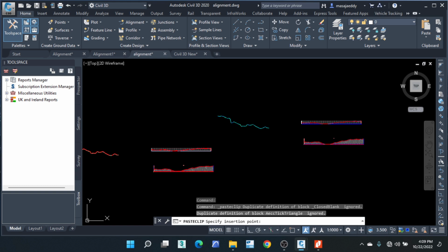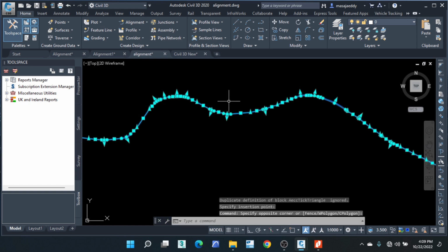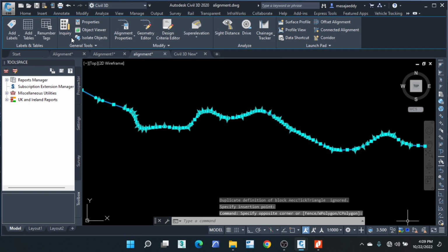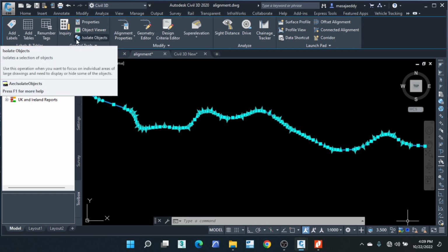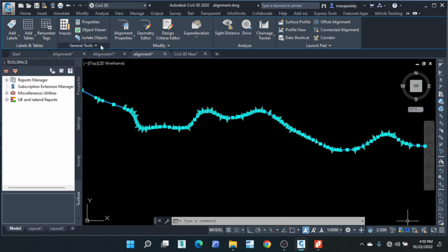I have a question. I just want to understand, when you talk of banking the road, does it mean it's elevating it? Yes, it's elevating. A normal crossfall from the standard is 2.5% either side, both on the left and on the right hand side.